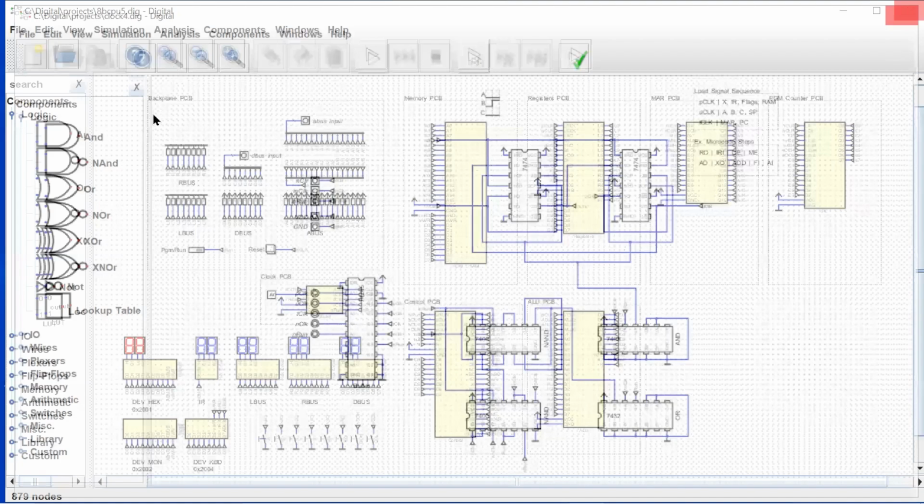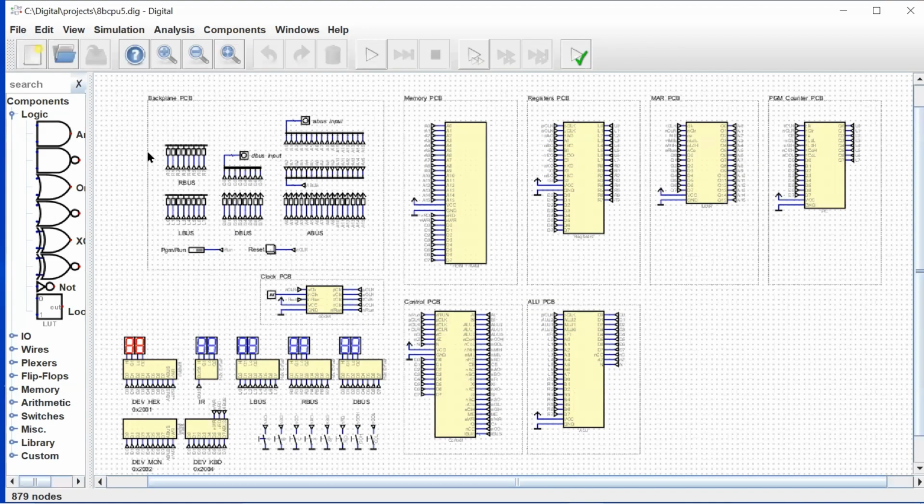Okay, and then our final board will be the backplane board, which is really just going to have all the bus pull-ups and pull-downs that are needed, a couple of buttons for the run program, and the reset button. Nothing really active on the backplane. The power connector, stuff like that will be there. All right, so that's what our physical design is starting to look like.